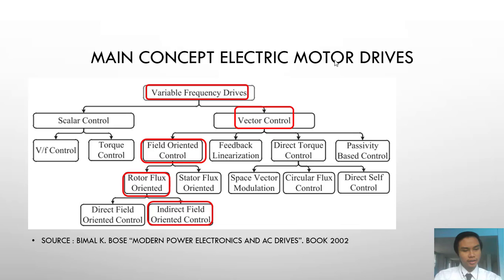The induction motor is the main concept of the electric motor drive. Here is variable frequency, then scalar control and vector control. Here I choose vector control, then field oriented control, then rotor flux oriented, and then indirect field oriented.